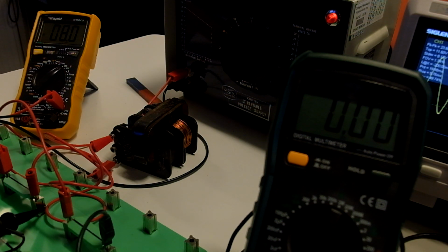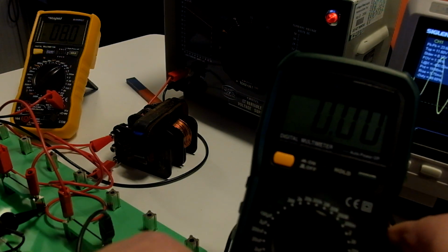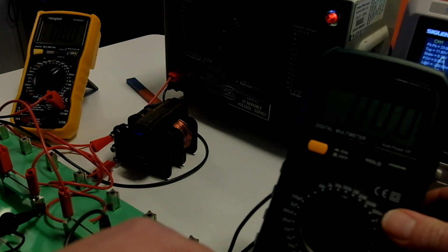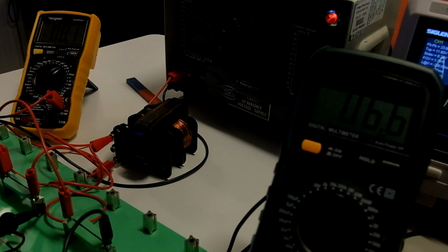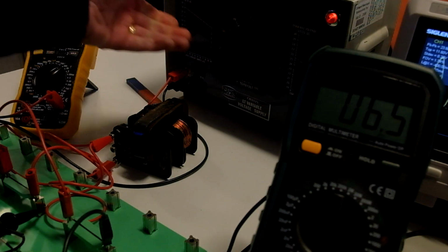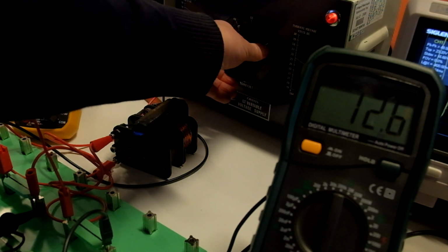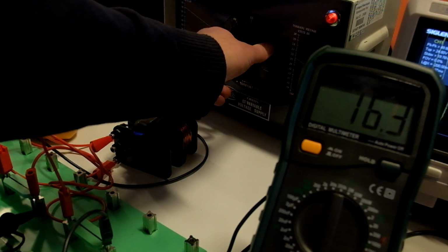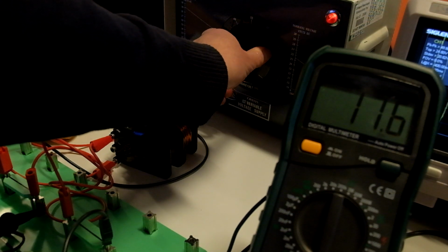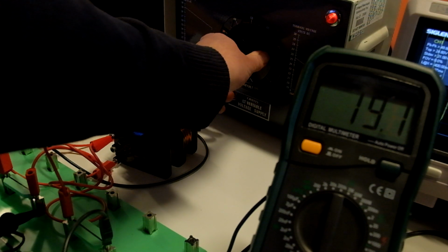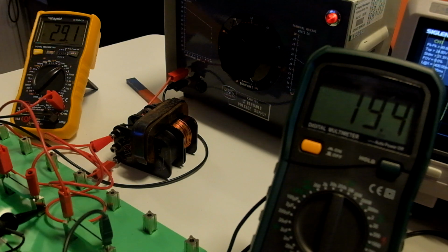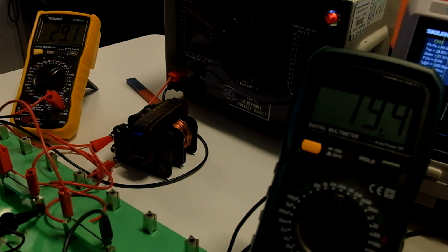We've still got the same arrangement, but the current will now be a lot smaller, so we're going to put it in there, and we're going to ramp up the voltage to pretty much maximum, which will be about 29 volts RMS. Okay, bingo, we got 29 volts. And we're going to redo the experiment but with the steel core.